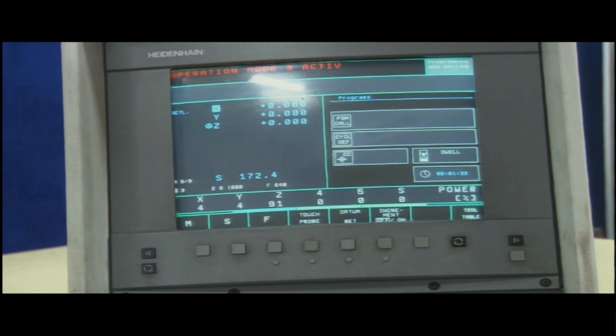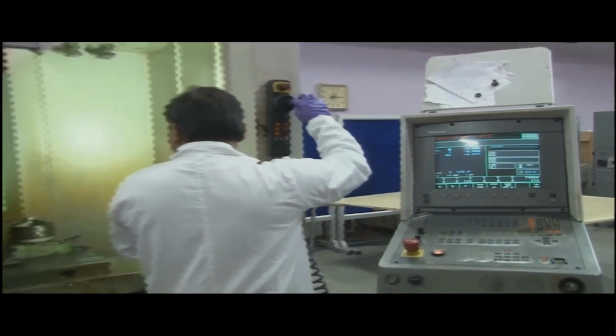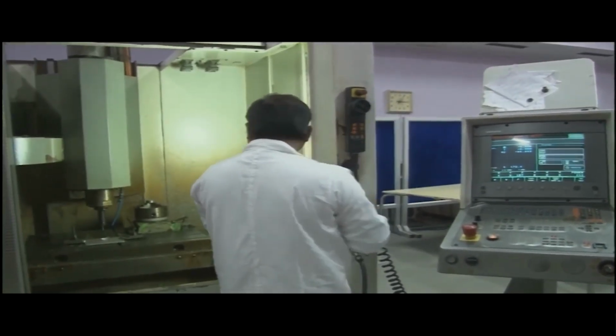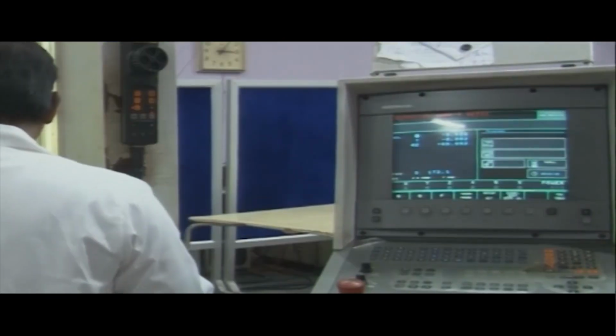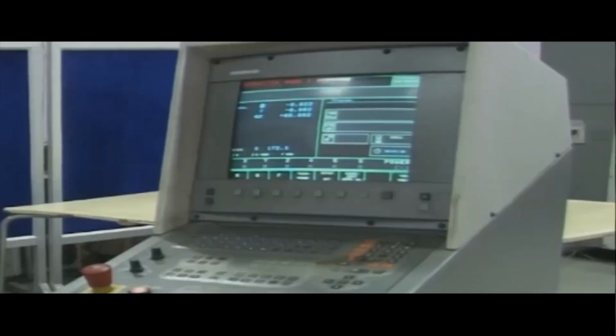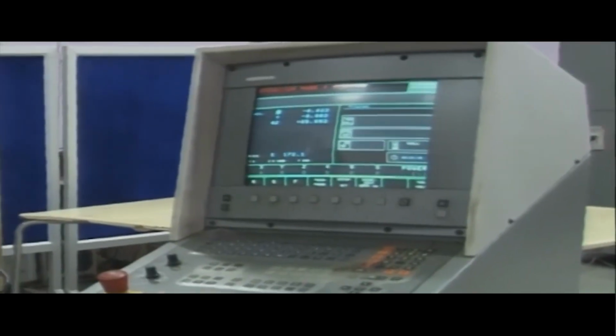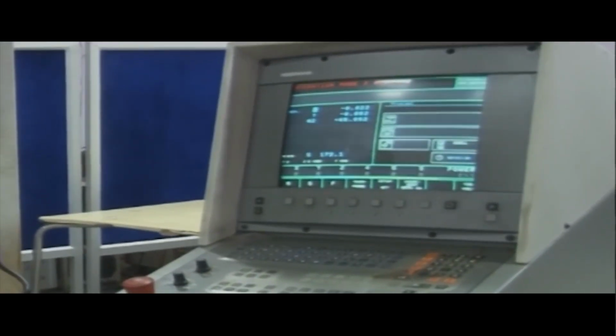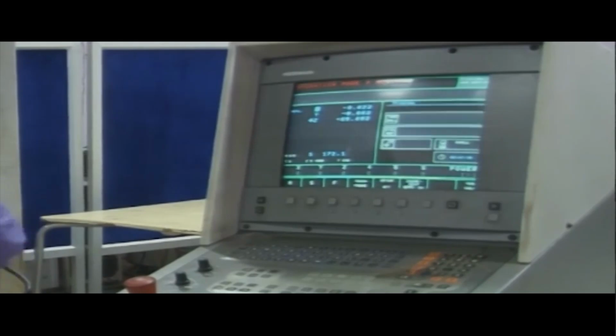This is also what would be understood by the software as the reference point. Now, the job reference and the tool reference are on the same page. The job center is 0, the same thing is done here. So, we can transfer the same code to this machine through pen drive, through internet or CD or DVD. There are certain ways, whatever our machine control accepts.